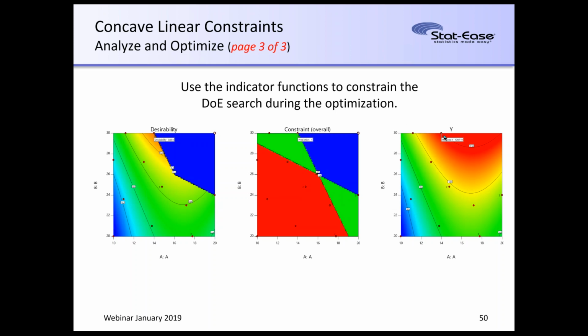So you can see then when I do the optimization, the function optimum is here, but it stops when it hits that constraint because we're now extrapolating into a region where we can't run. Okay, we can't run in that blue region. And because I have that constraint function in the optimization, it knows to stop when it reaches that point.